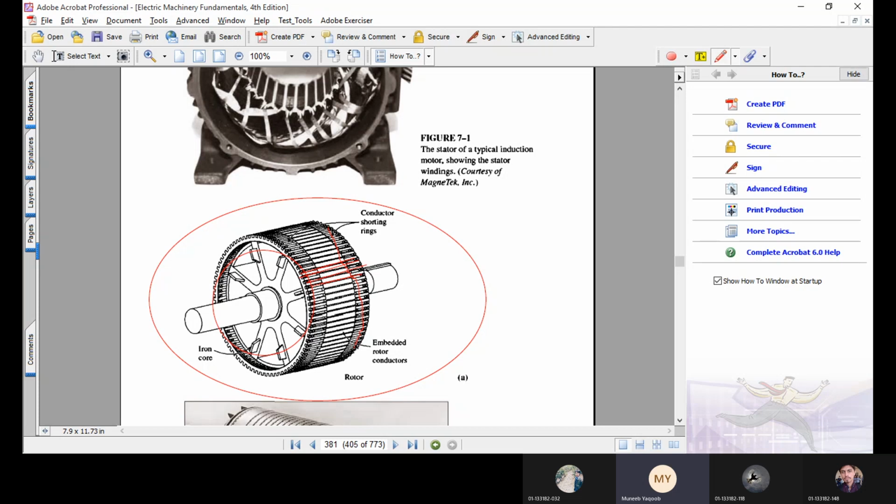So why are the conductors integrated in series? Because the voltage builds up in series. All the EMFs induced in these conductors will sum up to give a bigger, reasonable overall EMF.